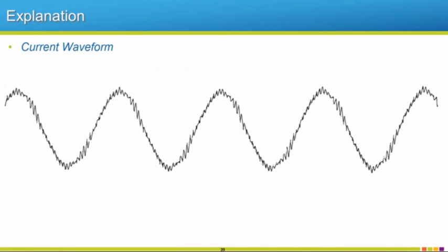We were talking about our voltage waveform before. If you look at our current waveform, it looks great. Our current waveform, I like to call it a shark tooth pattern. So voltage is instantaneous, so that's why it kind of looks like a square wave that's alternating. Okay, but current takes time to change. So whenever that IGBT switches on and off, it's going to go off, but it can't shut off instantaneously. So this middle point here, it takes time to shut off.